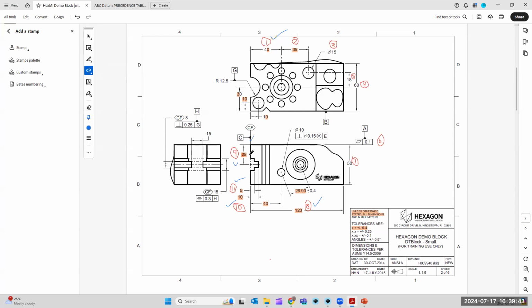This exists, right? It's plane C. But the right plane does not exist. Right. That surface doesn't exist yet. Yeah. So the trick here is you could make it a plane. You don't need to, because you can go from a plane to a point, and you can just get the distance between those two. So if you don't need the flatness or the perpendicularity or anything that requires a plane on that surface, you can just make it a point.